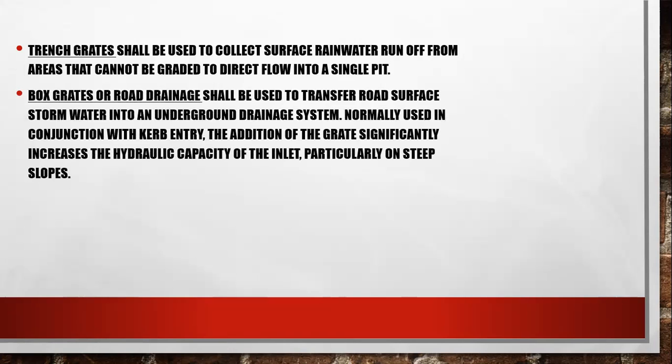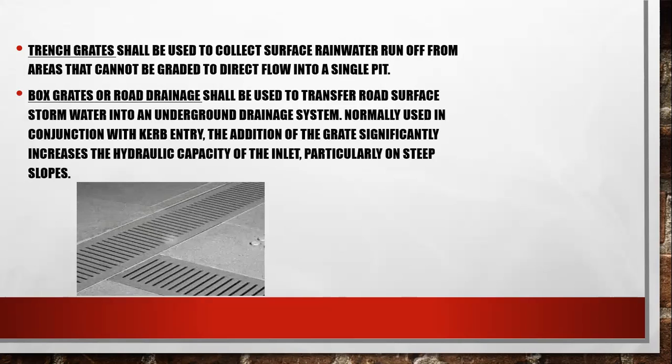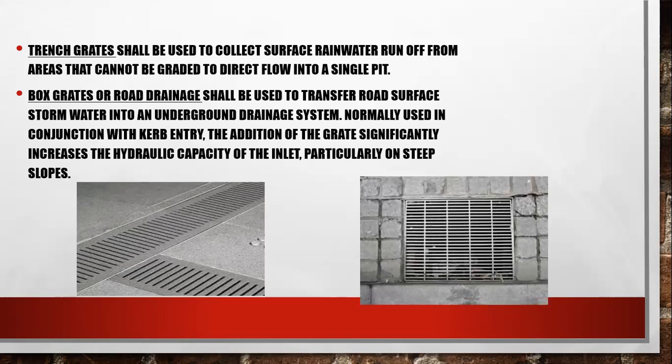Next is the box grate or the road drainage. Shall be used to transfer road surface stormwater into the underground drainage system. So this is the example of the trench grates. Next is the example of the box grate. From the word box, it is usually box-shaped.